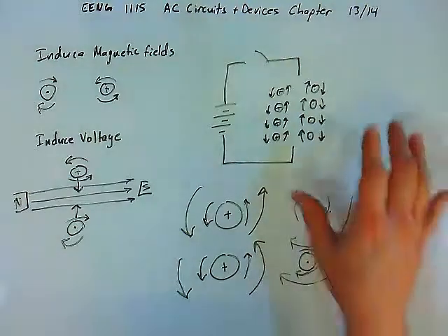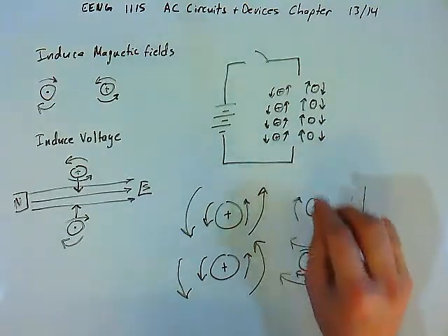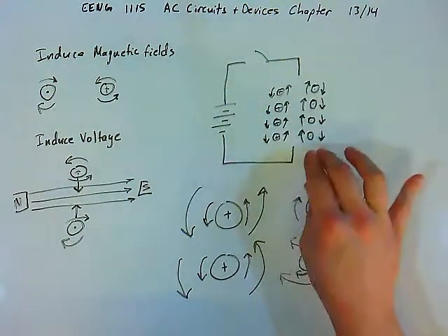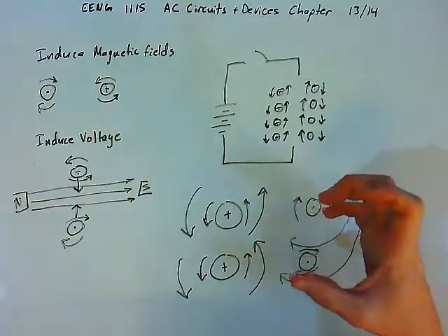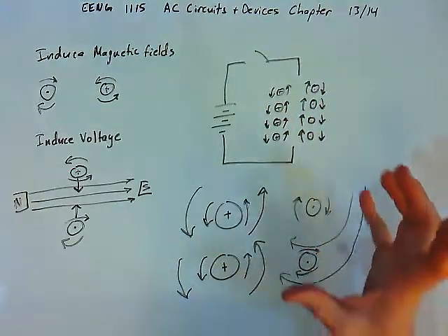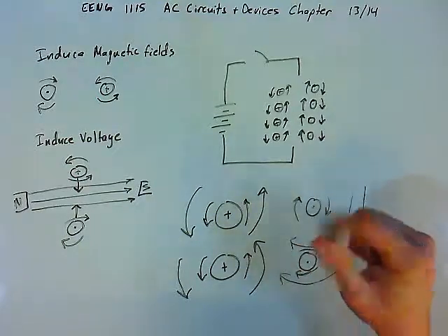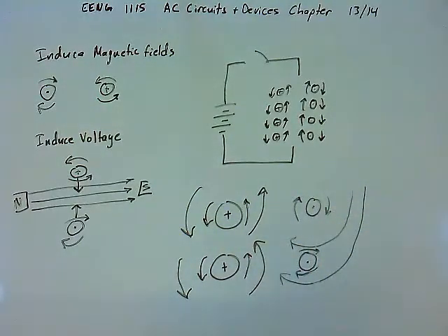The inductor is storing energy, and that energy is stored when the switch is closed and the current flows and these flux lines grow. The growing of those flux lines is the stored energy. When the switch is reopened, the inductor has those magnetic fields collapse and is trying to return that energy back to the circuit. So the inductor in that sense is an energy storage device.